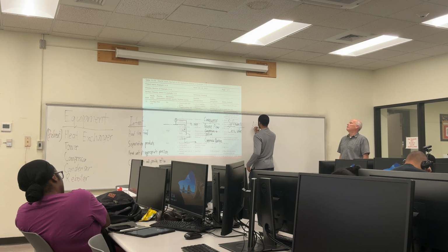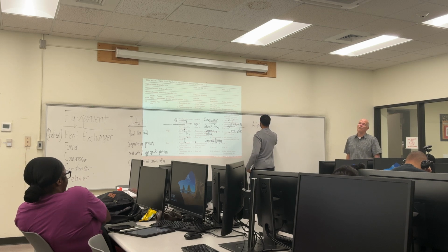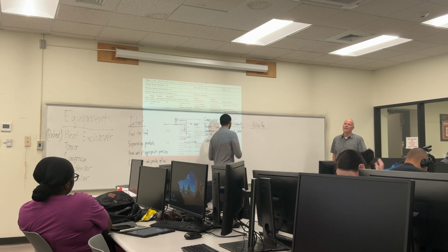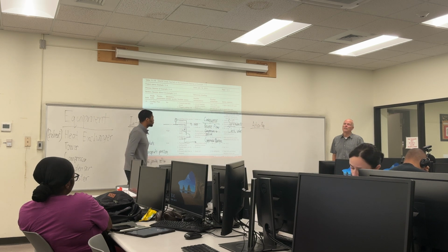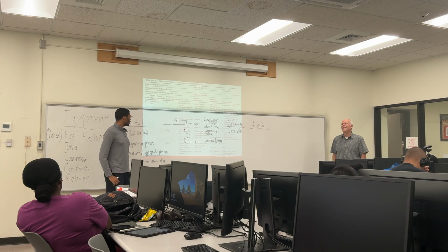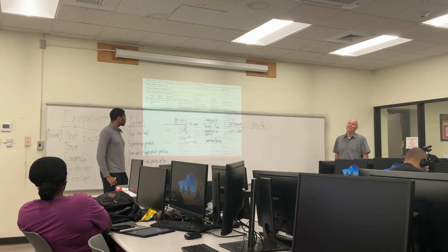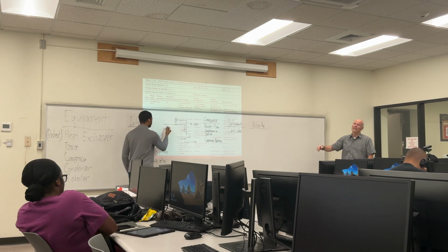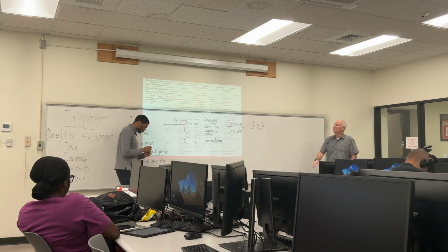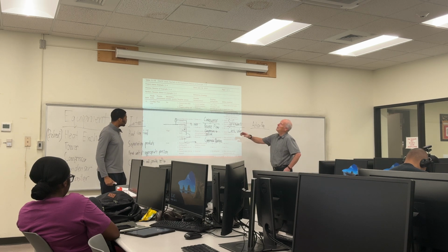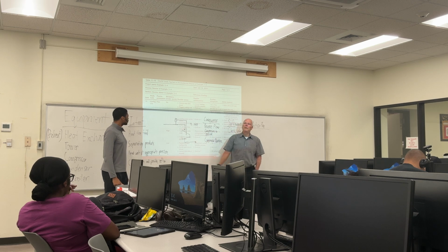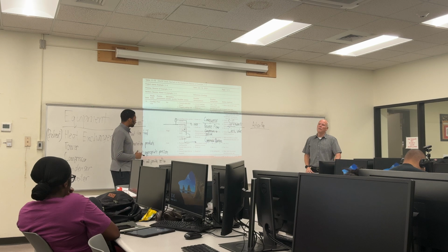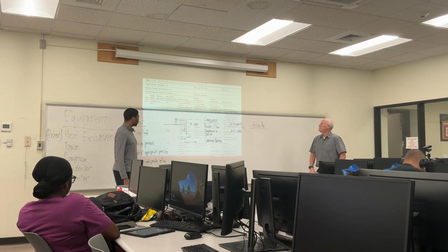Well, we need another safeguard first, though. How do we know that the compressor stopped working? If you're on a plant, how do you know the compressor stopped? If the inlet pressure and outlet pressure of the compressor... Well, that's one way, but that's not going to be very quick, because the outlet pressure is going to be bleeding back the other way, and the inlet pressure is going to go high, but you may not have that. So maybe you'd have an alarm on the suction pressure. Almost certainly you would have an alarm on the suction pressure.